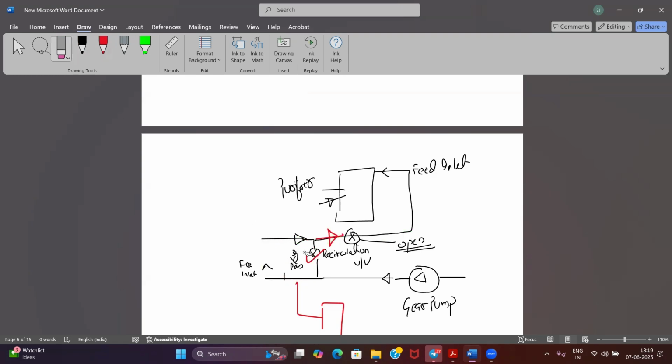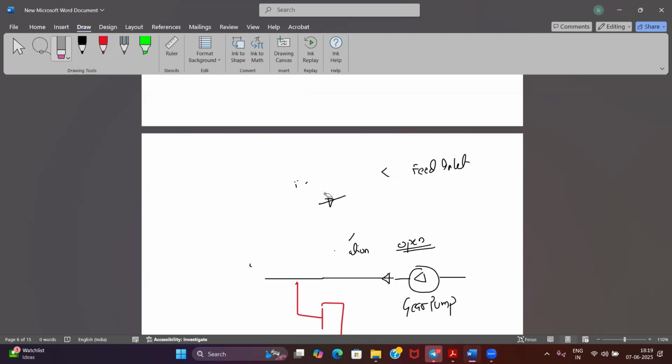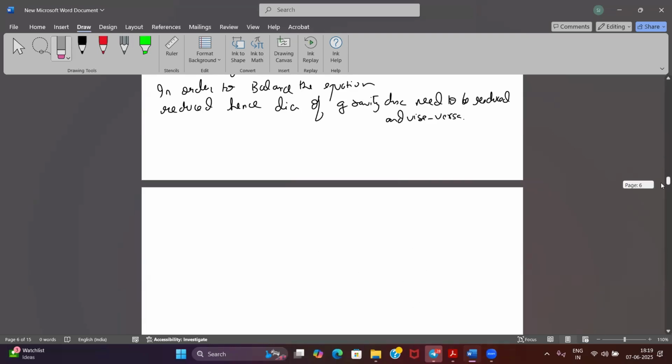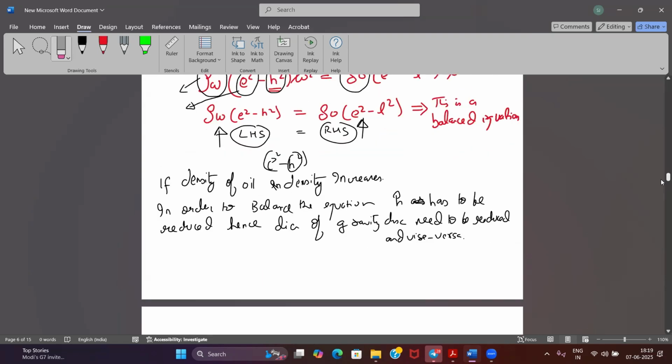Okay, so I will just erase this now. This is a function. I will come to all these things a little later. First I have to do the basic concepts. Then I will go into how the purifier is started, how it is stopped, and how it is desludging. I will tell you all the manual steps. Now, for auto, it will be solenoid operated, right? If I put a solenoid on that line, it will open my valves in auto according to the timer. Agreed?